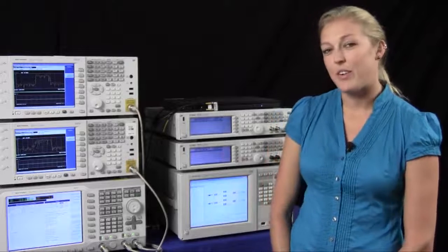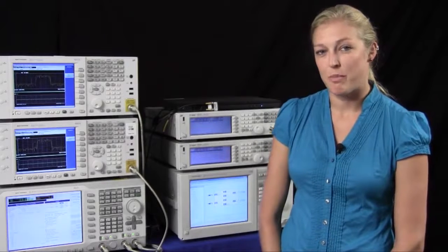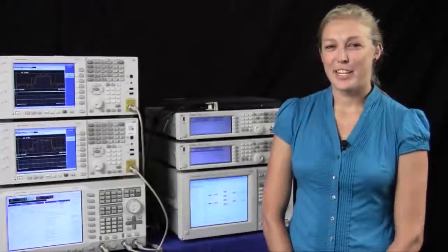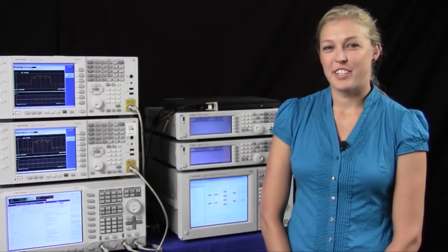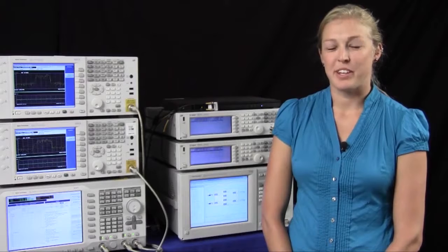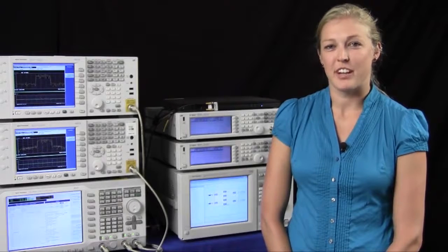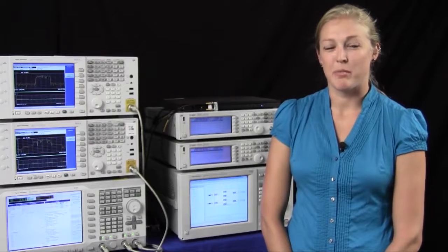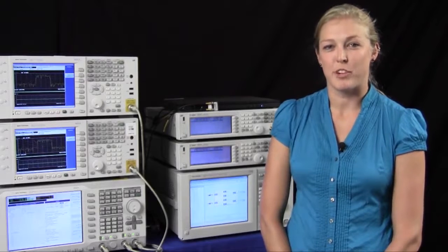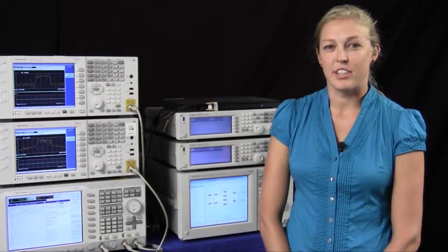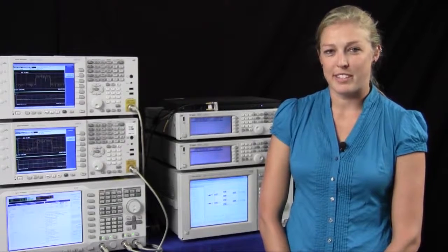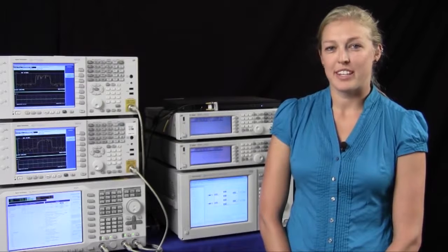I will now walk you through Agilent's proposed solution for MIMO OTA test, the two-stage method. The two-stage method combines the benefits of traditional anechoic chamber radiated measurement with the flexibility of digital channel emulation. This fast, efficient, and cost-effective method provides a solution for engineers to perform design validation test until 3GPP and CTIA decide which test method or methods will be supported for MIMO OTA test.